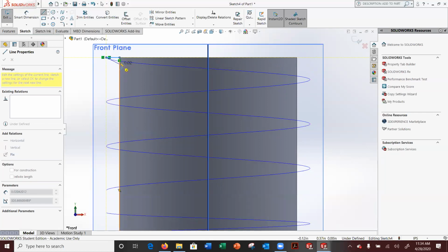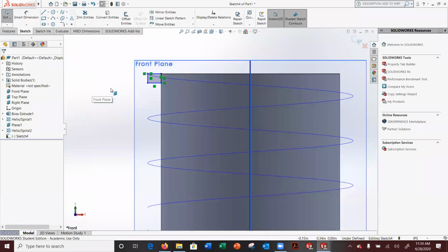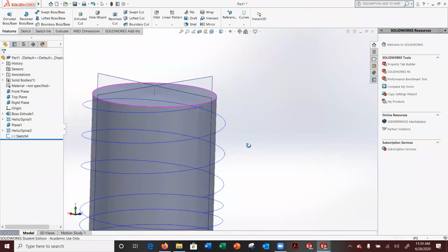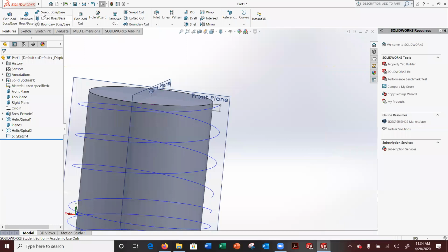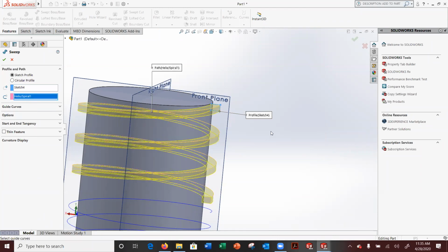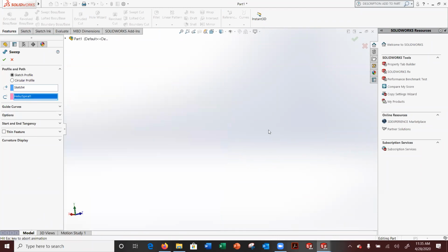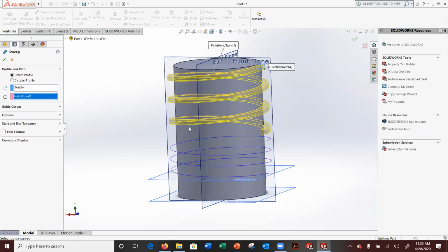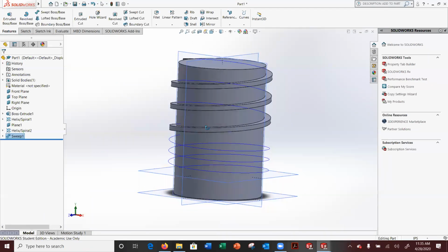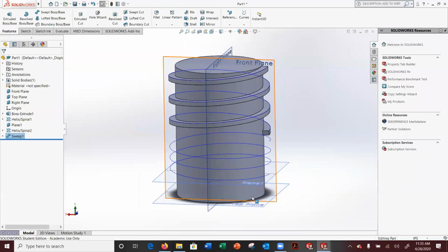So for example, if your shape looks like this, I'll create a rectangle here, and on the bottom one I'll create a triangle. There's your shape. Okay? This shape, now you can literally go ahead and sweep it, pick this shape, and send it down the slide, as I like to call it. Whoops. Sorry. And it just sweeps down, and that's it. When you hit OK, there is your thread. That's a square looking thread.